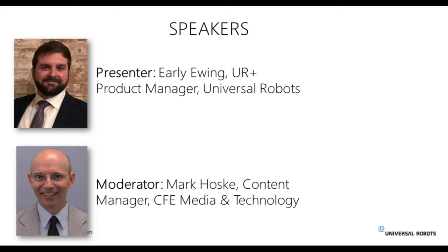We actually have a built-in force sensor on the E-Series of our robots, but we also have partnerships with companies like ATI and Robotiq that make force sensors that plug and play into the robot. The fact that it's collaborative doesn't restrict you to any type of end-of-arm tooling or anything you'd be able to do with traditional industrial automation. The UR+ platform and Universal Robots simply try to eliminate as many of those barriers to integration of those products and accessories as possible. That, again, drives down to your ROI, reducing those ancillary costs of the installation, enabling the same applications at a lower cost and faster return on investment.